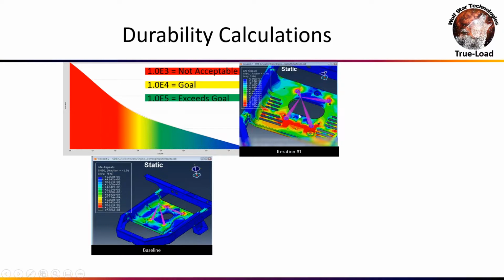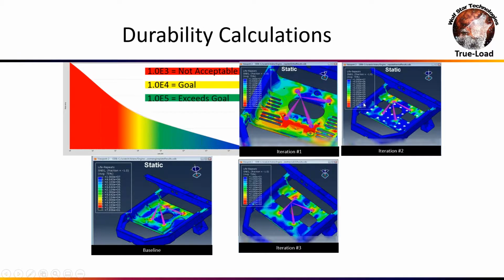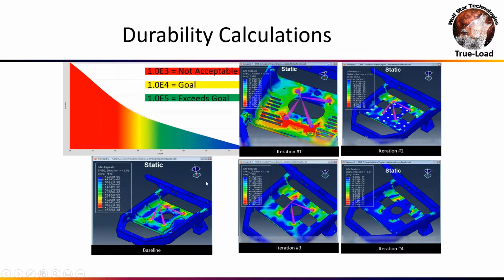So this was perfect correlation with the lab. And having that additional confidence, we then ran that fatigue calculation on all the designs. By the end of the week, we had a design that had the airflow they needed and actually improved durability over what they started off with. So this is what you can do if you really understand your loads.